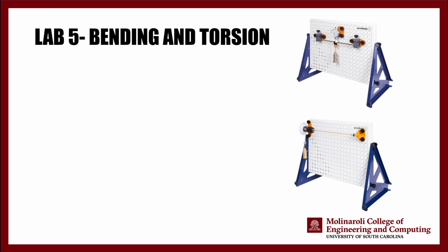So this is going to measure the deflection for us for different types of beams, and these are your supports. For the simply supported beam, you just have to make sure that these two are loose, so the beam can rotate, can move inside. And for the built-in beam, you want to make sure that these are as not loose as possible.